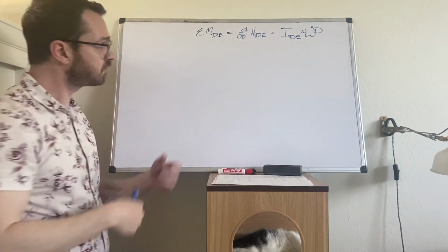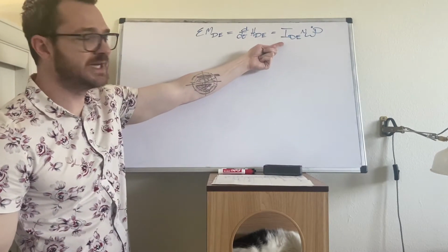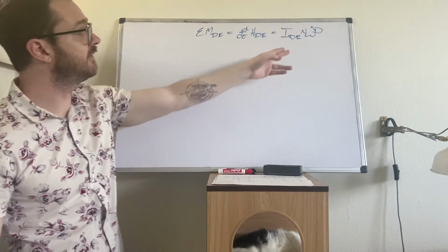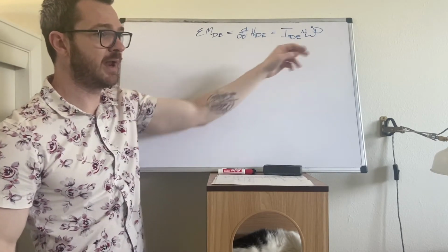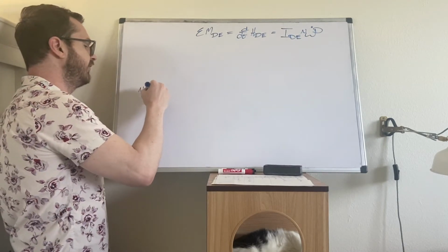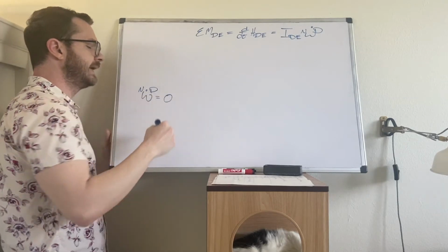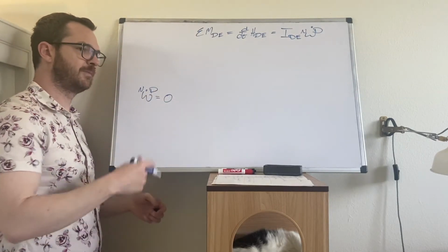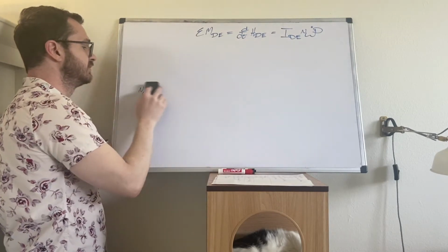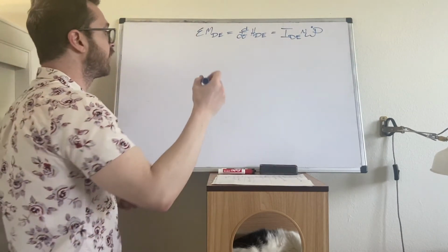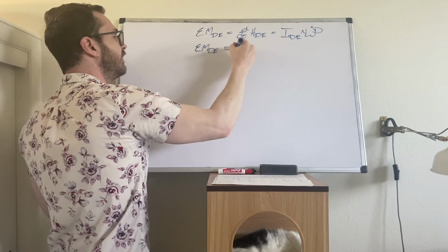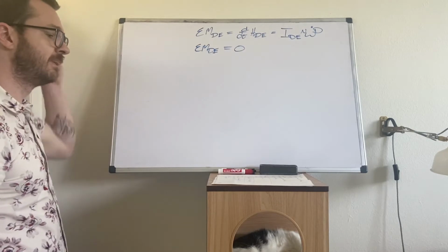Now, you might dig into this inertia term and apply the parallel axis theorem, but if you recall, when we did the kinematics, we said that we were assuming the handbrake did not rotate, which means that omega in d dot is 0. So the right-hand side of this equation, the sum of moments on body D about E, is going to equal 0 for this problem.